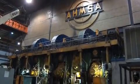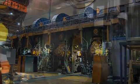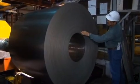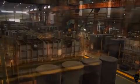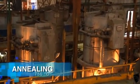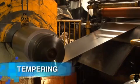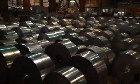Then the strip is cooled to room temperature in various mills in order to gradually reduce its thickness and achieve the desired specifications. In order to soften the material, the coil is annealed in a continuous heating oven at temperatures of up to 750 degrees Celsius. The steel strip then goes to the tempering mills, which give it a greater surface quality and the specified hardness required for the various applications.